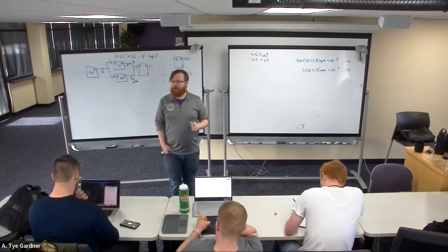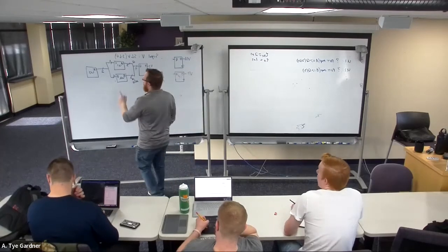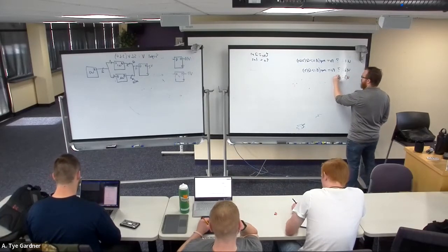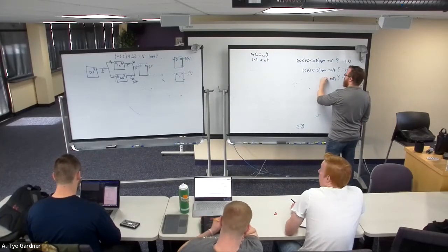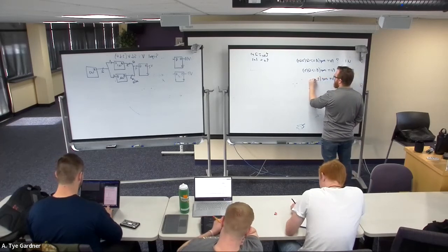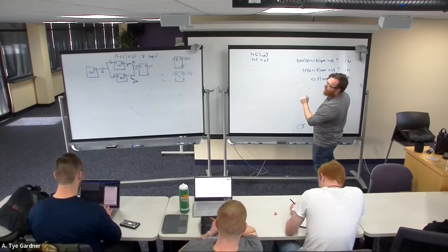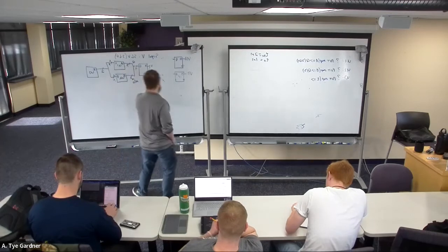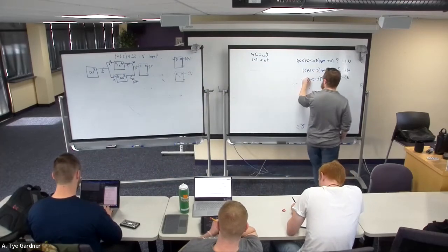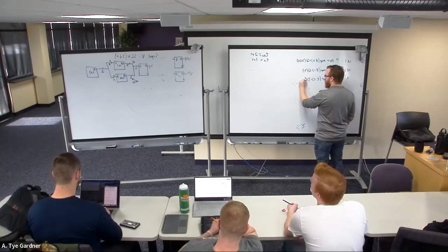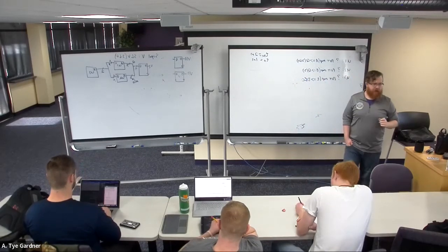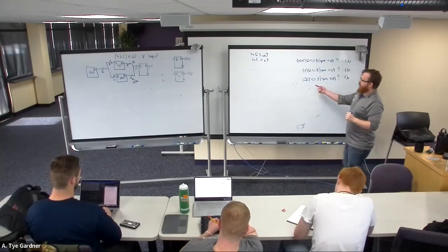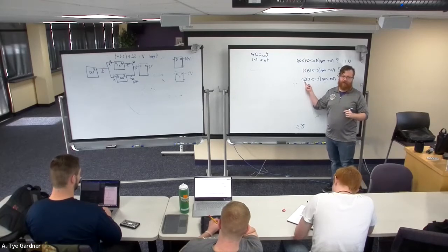If I want to do that, well, I cannot do this. This is what we would like to think about doing. U3 is whatever device, port map E gets mapped to, what do I call those? Oh, I haven't given, well, I'll call the signals the same, the D, C. Right, ampersand being the concatenate function, meaning stick the 2 together. VHDL does not like this. It will not let you do this. It will throw an error.